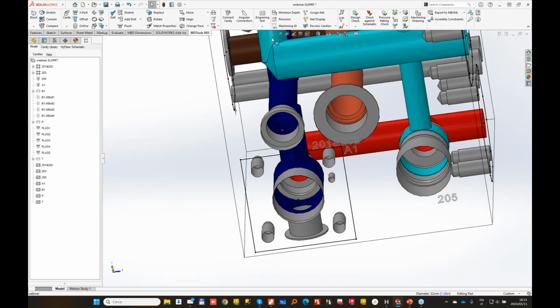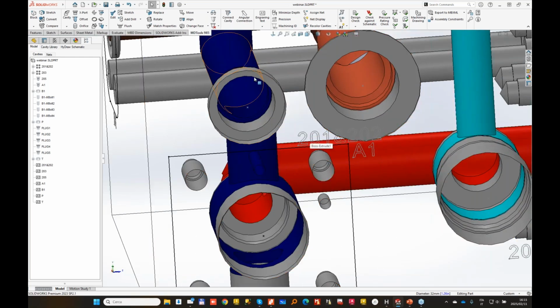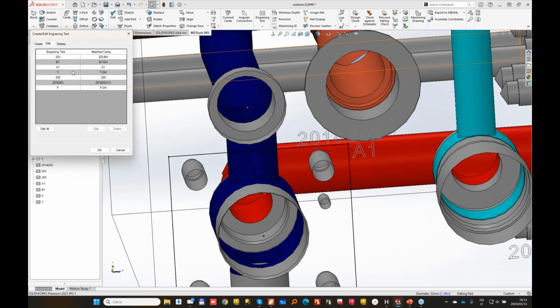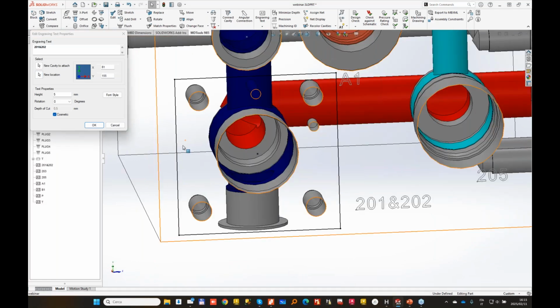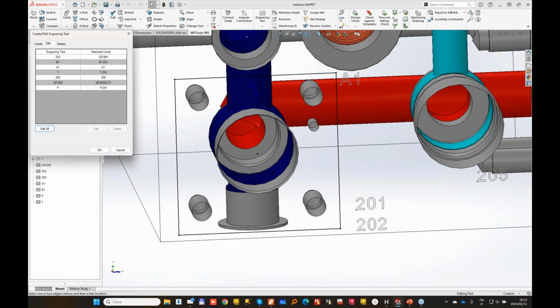As you can see, in case of overlapping engravings, we may need to relocate them, so edit. When we want to relocate, we can use the arrow keys to change the position. A faster method is really to pick a new location. In case of slip-in valves coming from Hydro, the engravings are grouped. If you want, you can put them into 2 different rows according to your needs, and then you can click OK or change the position. Now the position is good, so let me leave them where they are.